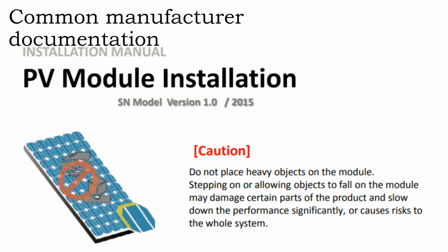Modules will fail by leaning them up against the wall, and the wind blows them over, and they smack on the ground, and they crack open all the module glass. What is more insidious over the long-term life of the project is if the installation was not installed well, but not in a way that damaged the panel up front.